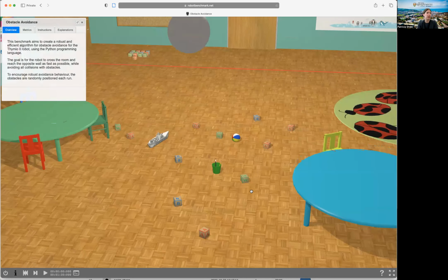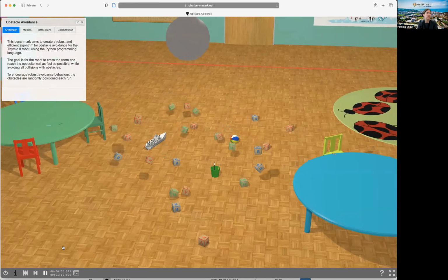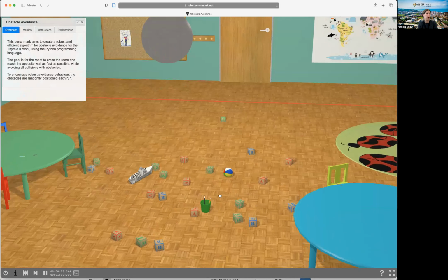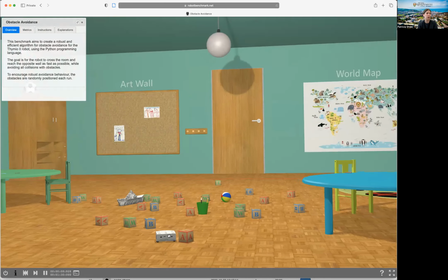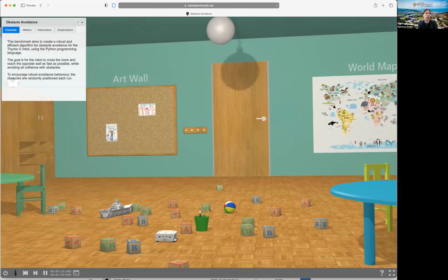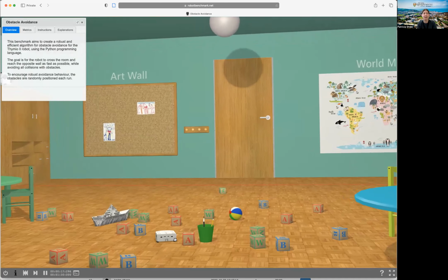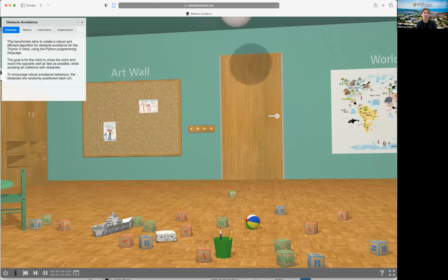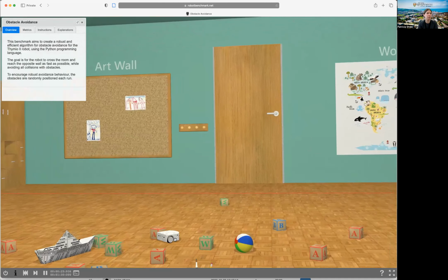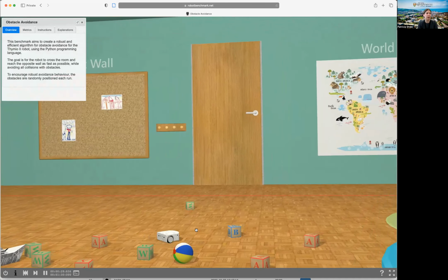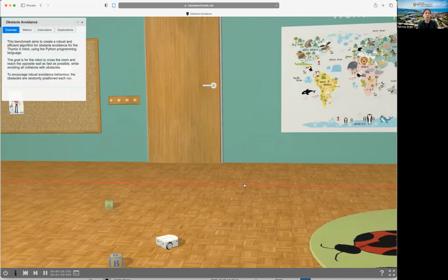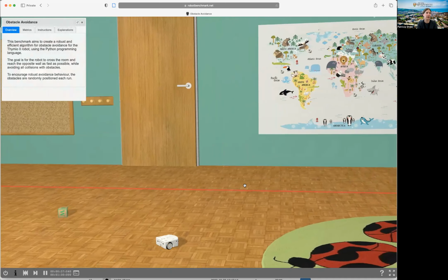Now, when I start the simulation, when I press play down here, it drops some additional blocks onto the floor in front of the robot, and we now see the robot is driving forward. It has some basic Braitenberg controller in there already, so it will do a certain amount of obstacle avoidance to be able to drive around. It's actually getting slightly further than it normally does on the default program. Normally it crashes quite quickly. But one thing you will notice, hopefully, quite quickly, is it's not doing anything at the moment to orientate itself towards the red target line.